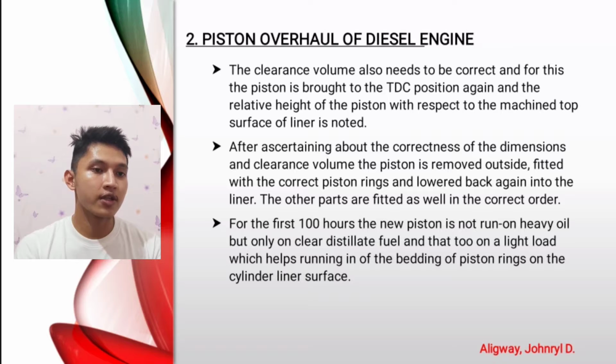And the last step is, for the first 100 hours, the new piston is not run on heavy oil but only on clear distillate fuel, and that too on a light load, which helps the running in, the bedding of piston rings on the cylinder liner surface.